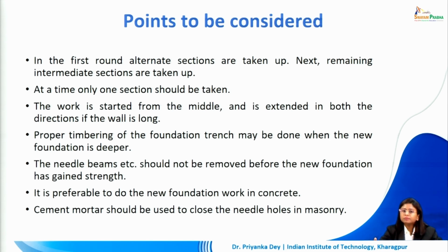The needle beams should not be removed before the new foundation has gained strength. So the moment the construction is done and we have moved on to an alternative section, we do not remove the needle from the previous section. We allow this foundation to gain its strength, settle, then we remove the needle.